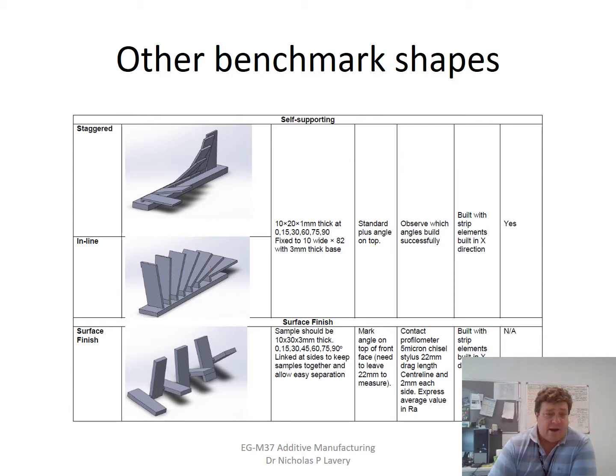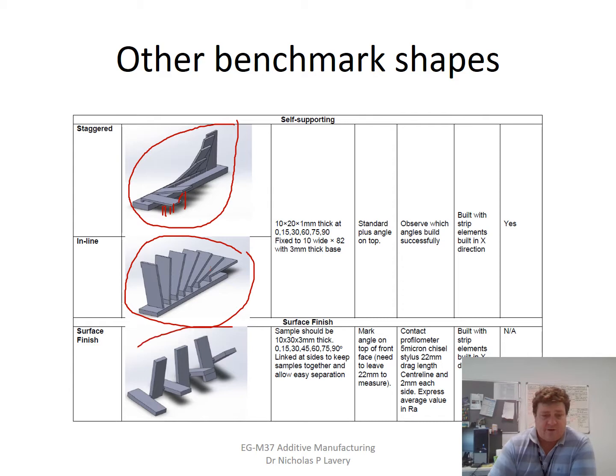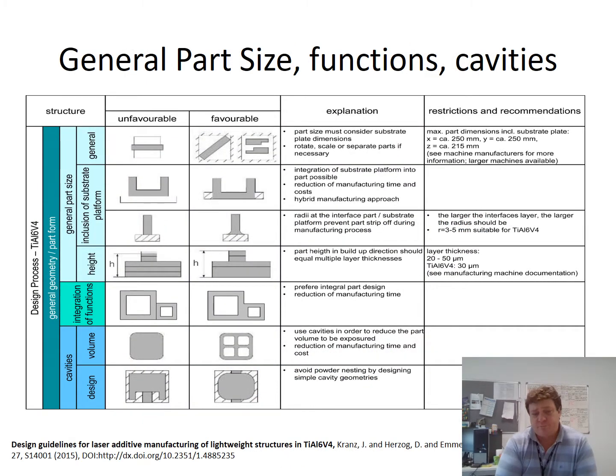And in order to put this part on the plate as it's looking there, you will have to put support structures here, here, but some of these will self-support. Okay, and it's not necessarily 45 degrees, so finding that lower critical angle is important. So there's another best case there for very much the same thing. Here we have something which we're doing, looking at the surface roughness on both sides, can be measured with a probe afterwards. Determine that.